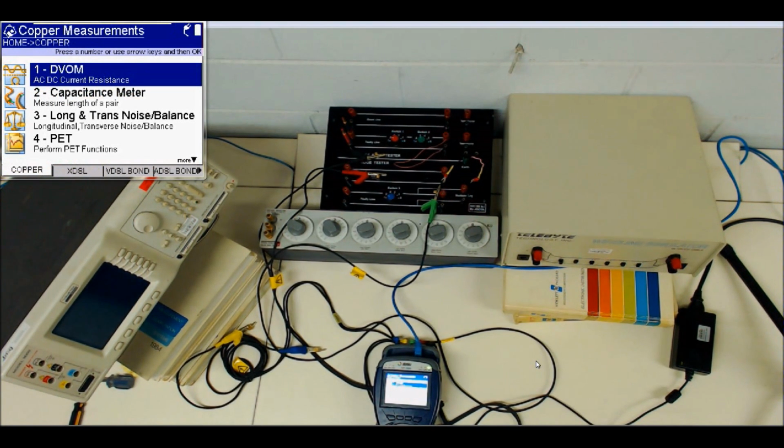Now, my friends, I'm going to explain to you how earth short circuiting becomes a problem to our lines under test, and how we can overcome this phenomenon with the precision of the instrument by using the functionality of the instrument. An earth condition would imply that both legs or one leg is grounded to the earth, so it's being short-circuited at some point along its length to the earth.